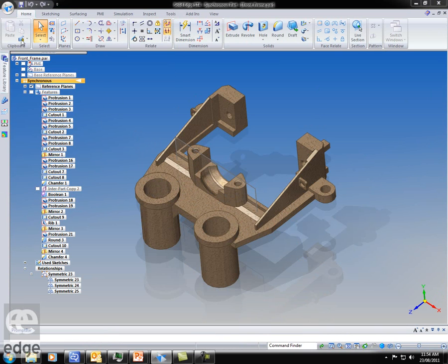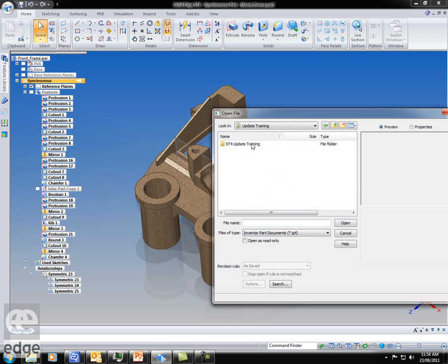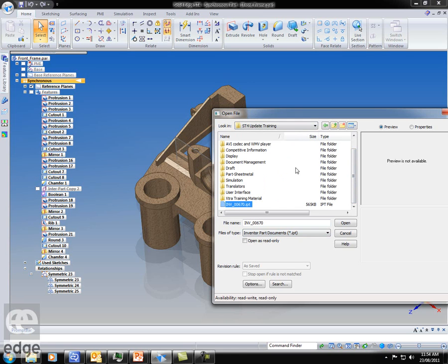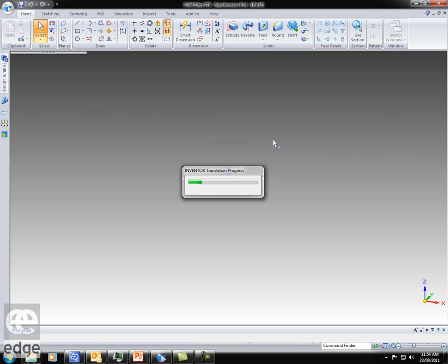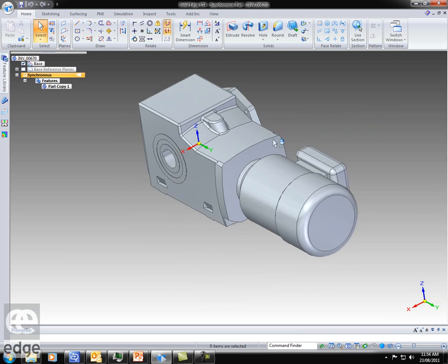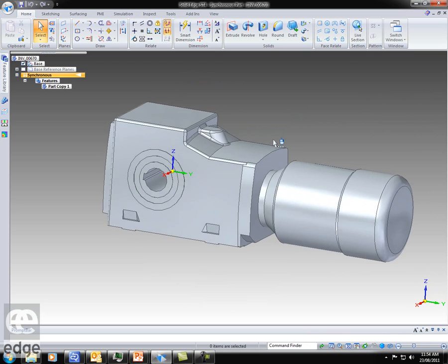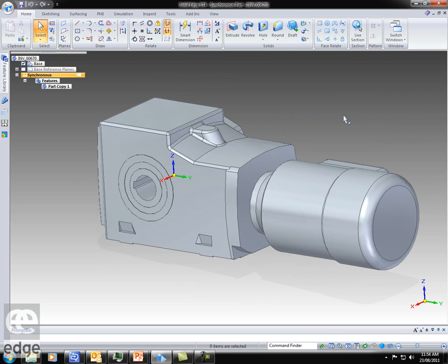So it's an open. We want to open here, and it's in there, I think. There it is, an IPT file, so we can open parts and assemblies. It'll automatically translate them into Solid Edge. So we just say open on that. Because it's a part, I'll just use a part template, and it translates it. If it's an assembly, it'll build all the part files for us automatically in the assemblies. Everything will come in grounded, but as you know, we have tools for creating things. So in it comes, and we can modify it, do whatever we wish to do to that, as we can with any imported part, but it's just now direct, which is quite a bit nicer.